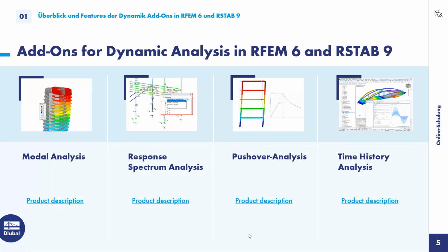The next thing would be the nonlinear static analysis, the so-called pushover analysis. That means the structure is pushed from one side and the load is increased incrementally. With that, we can also consider nonlinearities. Therefore, it's called a nonlinear static method. In the end, we get a force-deformation curve, the capacity curve of the structure, which itself is a great tool for engineers, since you can simplify your complex structure to just one graph. So you can compare it with a single degree of freedom system. The comparison with single degree of freedom systems is also used in this pushover analysis.